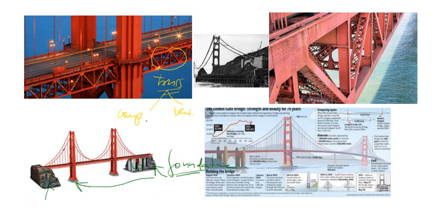This is called also anchorage, and it is used for the main cables to come there. These main cables come into the rock for the anchorage point. Look at the details here of the trusses. So this is the truss, and look that the cables are connected to the nodes of the trusses to avoid bending forces, as I explained in class.